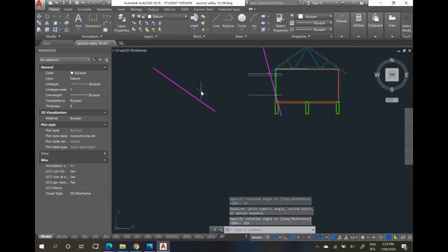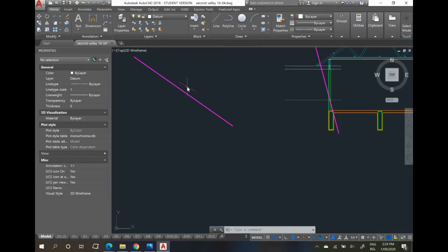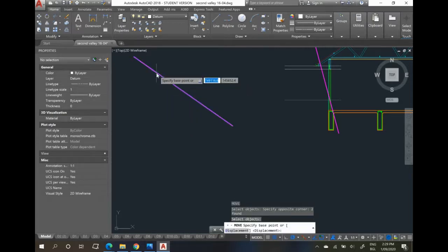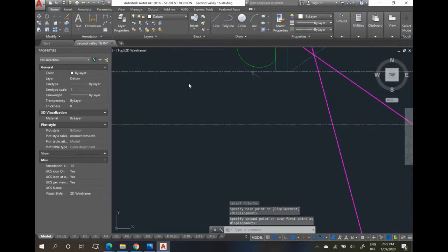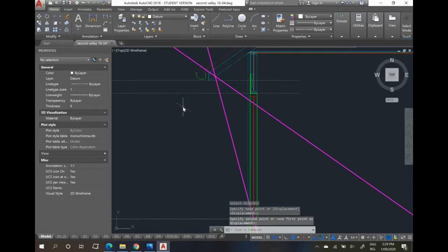So there we go. I've just given it 35 degrees. Once again, it's not the actual sun angle, somewhere an approximation of, but I'll leave those inputs to you to determine from your summer and winter solstice and using the sun calculator. But I'll move that one across as well. Let's come up here, and assuming we've moved our eave, that's our sun streaming in through our window there at winter.